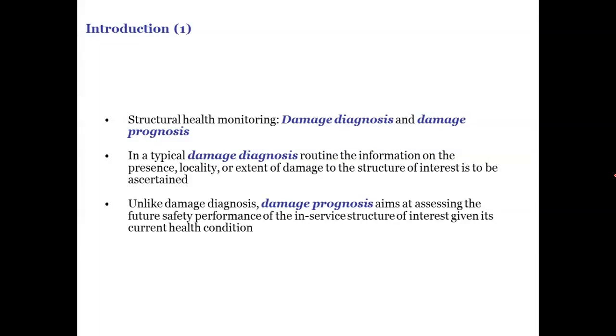In contrast, structural health monitoring is a task that is to be performed throughout the entire service life of a structure. So that's the difference. Structural analysis and structural design are performed before the construction starts, and structural health monitoring typically accompanies the entire service life of a structure. The task of structural health monitoring consists of damage diagnosis and damage prognosis.